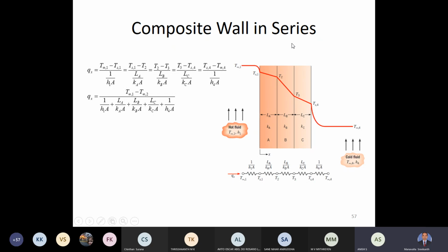When we say how to treat it in heat transfer, we will always be interested in finding out two quantities. One is what is the heat transferred, that means how many watts of heat has been transferred. The second important question is what is the temperature distribution. So these two questions are important in heat transfer. A third question may also be important. You may be asked what is the heat flux, not just heat transfer. Heat flux is heat transfer divided by the area.